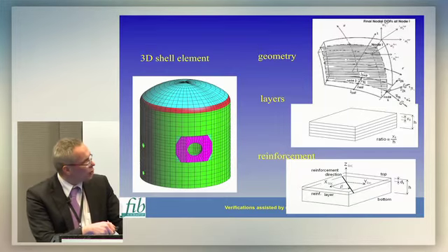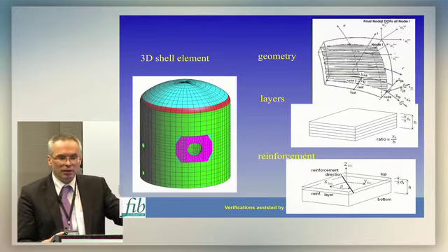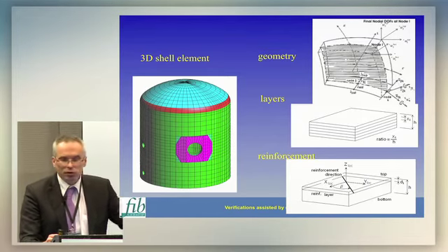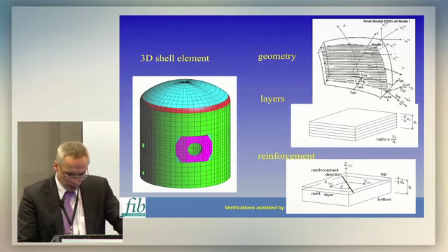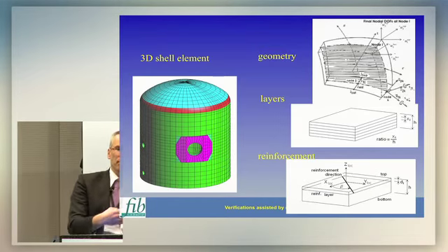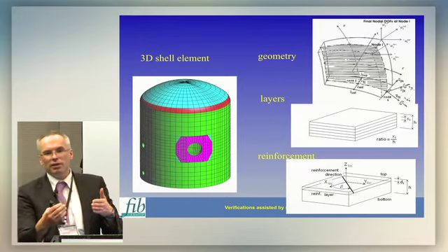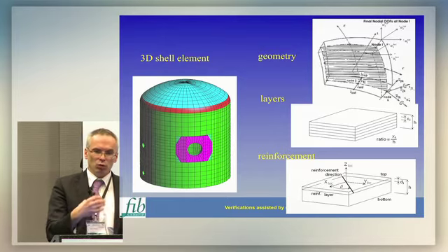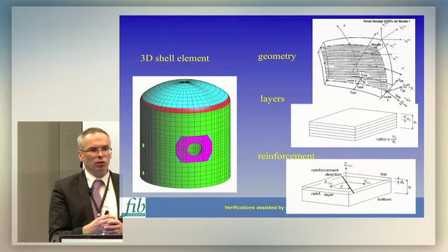This is the description of the plate elements. So what we like to use is the plate elements or shell elements, which are actually 3D elements. Internally, they are formulated as a shell element, but they have displacement degrees of freedom only. And this then makes it very easy to connect such an element with volumetric elements, for instance, for the ribs or for the foundation. So in this way, one can easily use bending elements, that means shell elements, in the areas where bending should be important, but in the areas where we want to capture shear failure, there we can use solid elements.